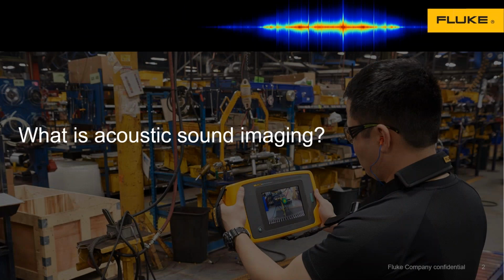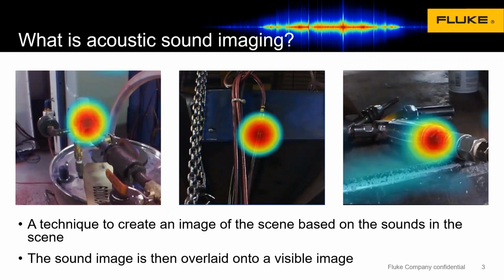So what is acoustic sound imaging? All right, I want to say that right now, keep in mind that acoustic, when we use that term for Fluke and for the i900, includes both the sounds you can hear, the sonic sounds, and the ultrasonic sounds, the things above human hearing. And we've developed a technique in order to listen for those sounds with an array of specialized microphones and then process them so we can create an image of where that sound is coming from, based on the frequency of the sound and the decibel level of the sound, how loud it is.